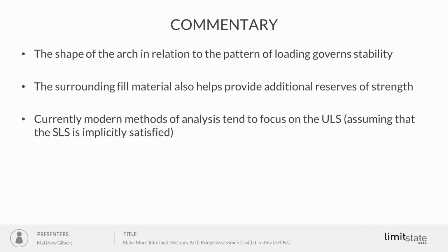Particularly, for example, on the railways, we might have a transition from short wheelbase wagons to long wheelbase wagons, which can have a very different effect on the masonry arch bridges that they're crossing, even if the axle loads are much the same. The other thing I've not mentioned is that an arch bridge is much more than an arch barrel. We also have fill surrounding the arch barrel, and that helps provide additional reserves of strength.